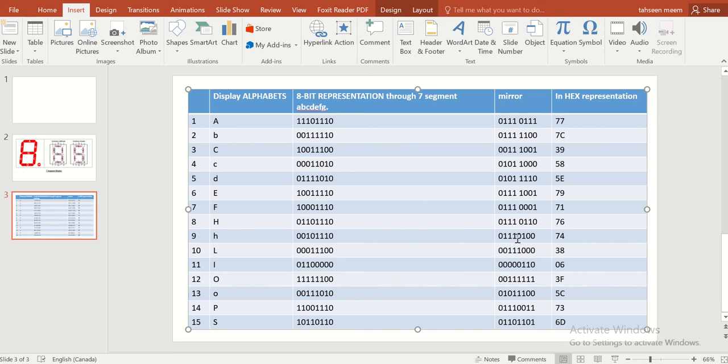So these values, you might have a question why we are going to take these values, because these are the values we are going to place while defining the array size, okay. We are going to use some functions for our Arduino coding. So we are going to write the code inside Arduino software. As you can see, this is how you can make one table out of it. After this table is done, you already have your hexadecimal values, okay.